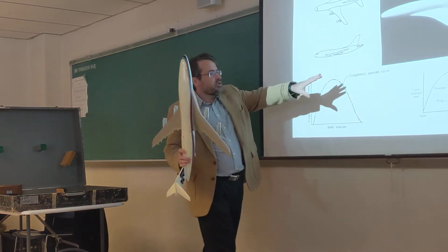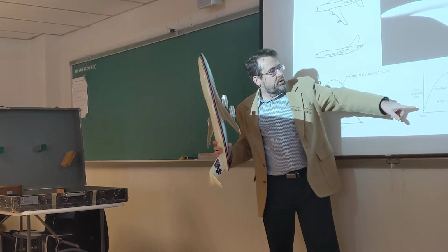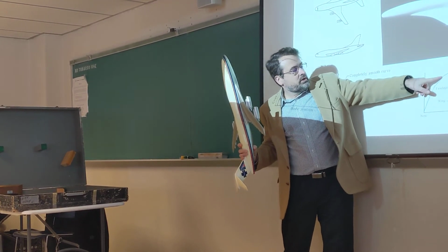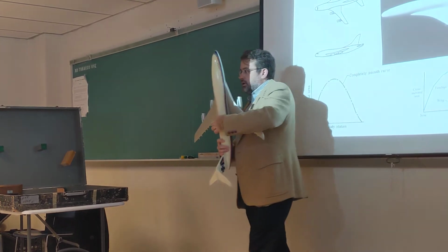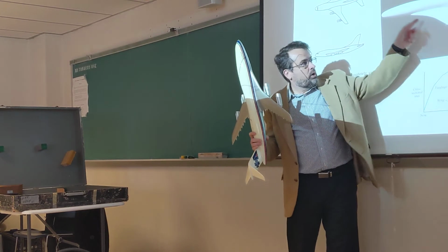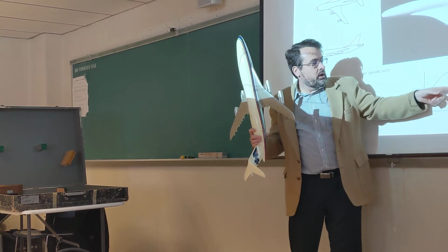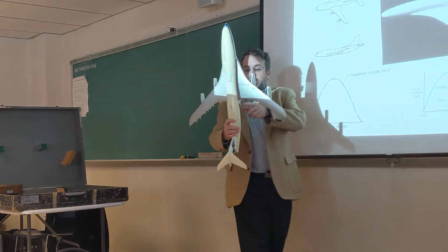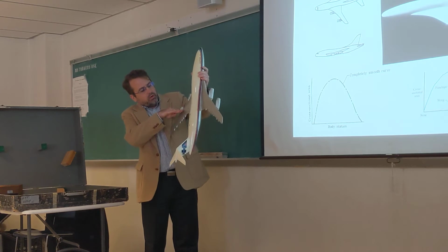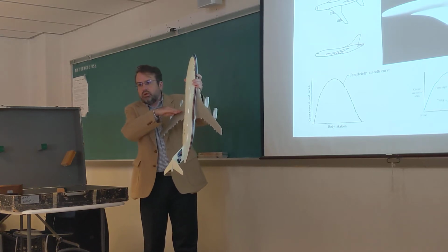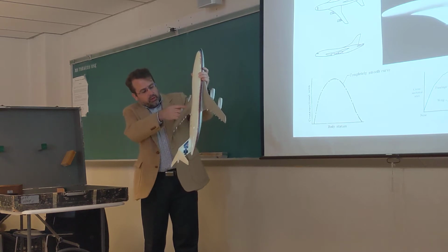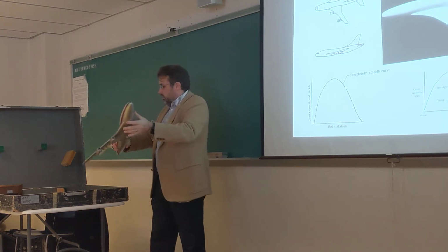And so this essentially follows that same approach. You'll notice what's happening here with the cross-sectional area of the fuselage. It gradually increases and then drops down where you have this wasted area, this Coke bottle-like midsection, as your wing is starting to increase the cross-sectional area. Then you increase it again as you get back towards the tail, where you're losing that wing area. Because if you look at it, your maximum wing cross-sectional area is usually going to be right around here somewhere, where you have the beefiest part of your wing, but then later on you start dropping it off in these later sections.